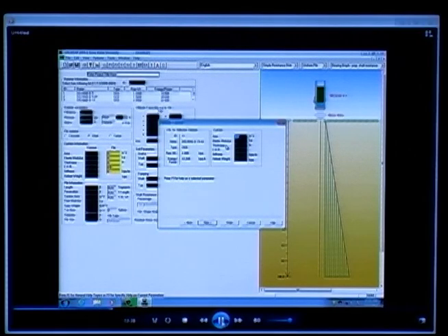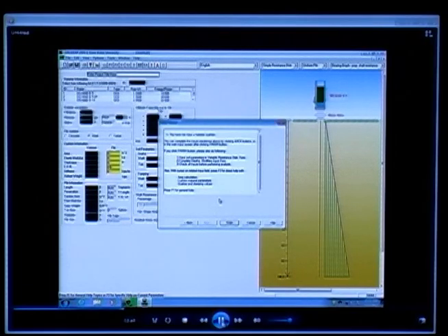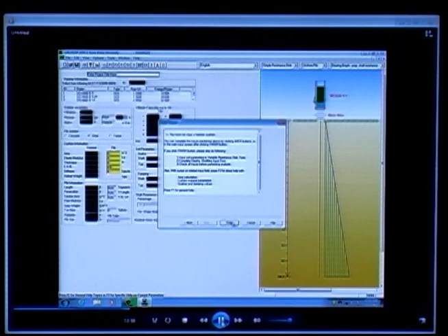For driving a steel H pile, hammer cushion is neglected here. So I want to highlight that actually the hammer cushion should be included as part of the analysis. So I will revise the video, but in this example, the hammer cushion information was not included. However, you could input the hammer cushion information if desired. Press Next to continue. The default resistance gain-loss factor of 1 is chosen for both shaft and toe. Press Next to continue. This page provides you some comments about your input. Also, you could click back to edit your previous inputs. After confirming all your inputs, you can now select Finish.